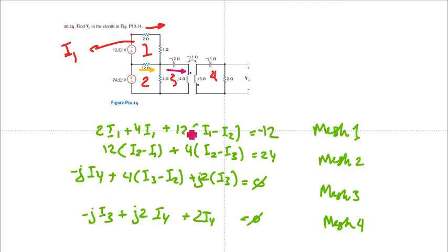And we have the magnetic coupling constant, or mutual inductance I would say, which is minus j1 ohm. And so now we have the dot convention. We need to pick another direction, so let me just do it really quick here, using the blue. For mesh 4, we assume the direction is going clockwise as well.